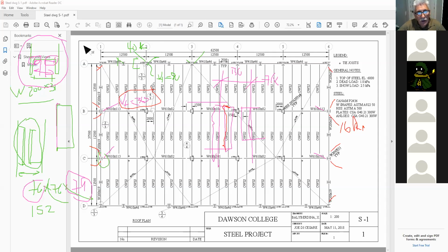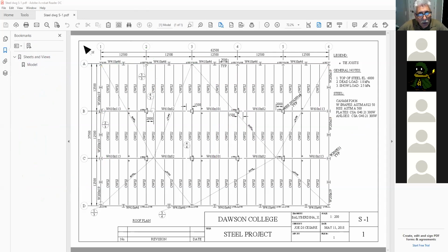And as a matter of fact, in this case, Gianfranco, let me just clear this drawing. Here you have a cantilever, okay? So this is a completely different animal than what you have in the beam weld tables. You follow? I wouldn't be able to use that table, because here you don't have a simply supported beam. Here the beam is a cantilever. So you wouldn't be able to use that table.